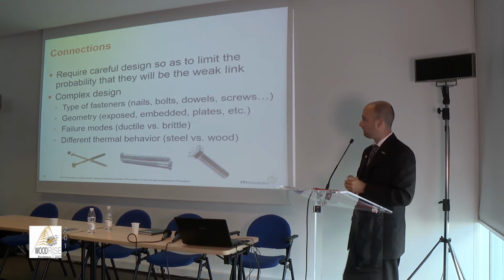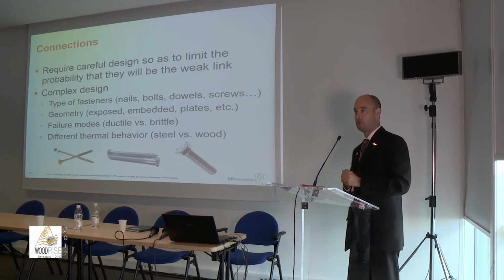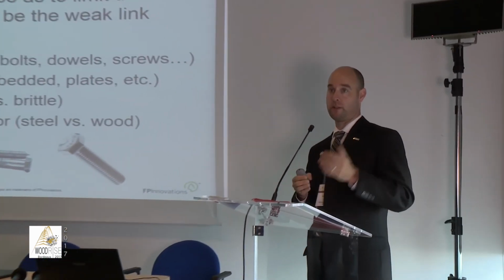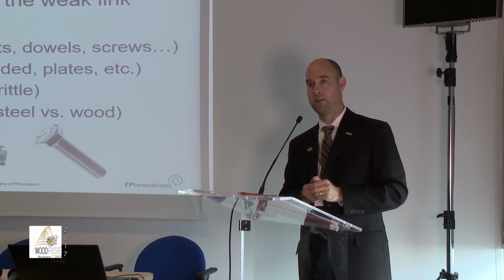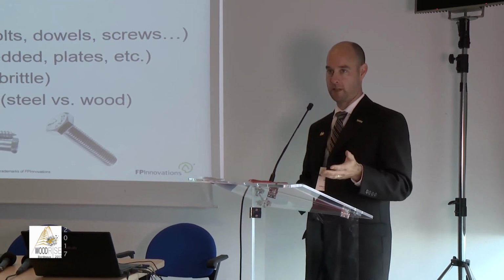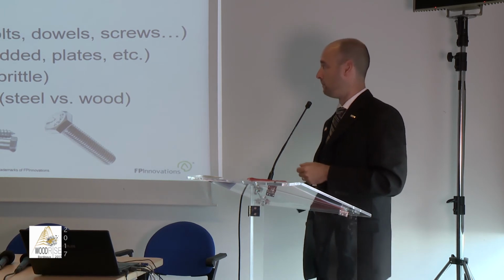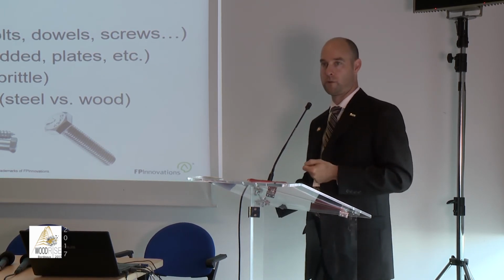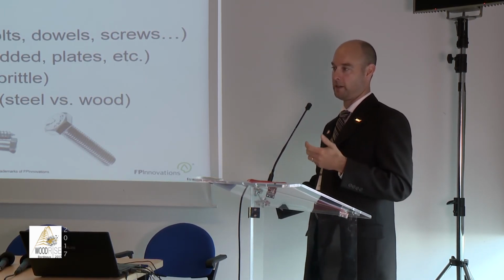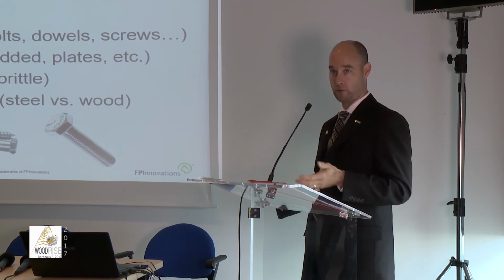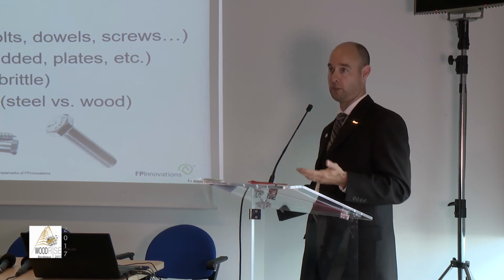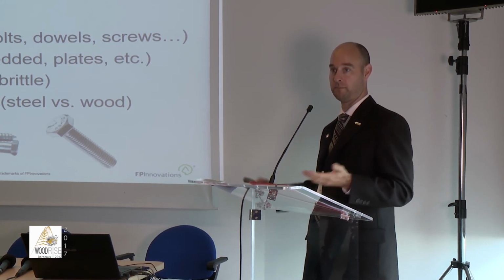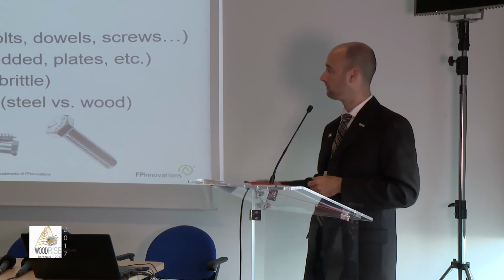Last point, connections. I don't have much to say on connections because we know that there's still some gaps to learn on how to design connections for fire design, especially for 90 minutes and 120 minutes. But they also do require special considerations. We can evaluate a beam for 2 hours, we can evaluate the column for 2 hours, but if the connection between them is 15 minutes, it doesn't give us much.